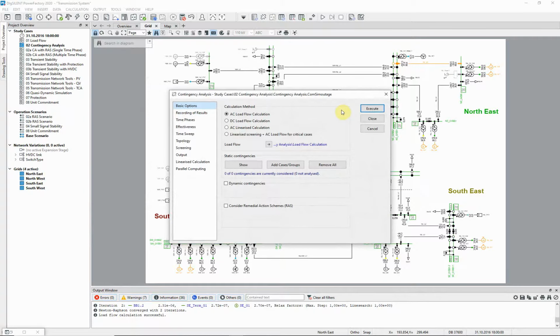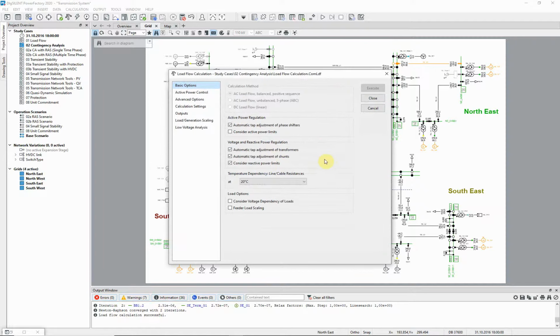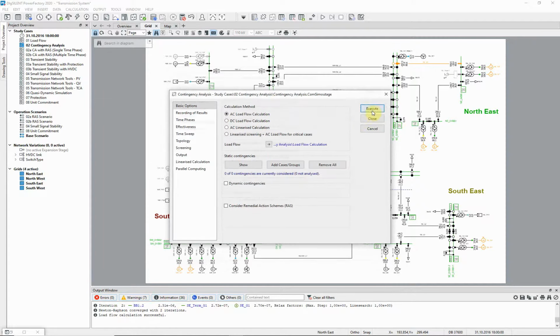There are three main calculation methods. The first is a calculation using a full AC load flow. The second is a fast DC calculation, which calculates active power but uses nominal voltages. The third is an AC analysis method that represents the contingency case by using equivalent injections to reduce the flow through the faulted area to zero. This speeds up the calculation, so can be useful for large numbers of contingencies, but it is a more approximate method.